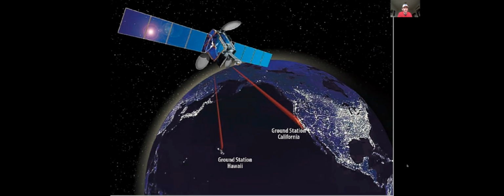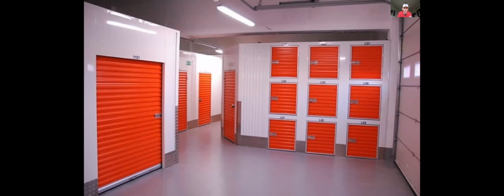So then one more big thing that's pretty important is having some sort of storage mechanism for storing data on your satellite, because oftentimes data collection and data downlink are separate on a temporal scale. So you need to make sure that the data you've generated is stored safely so that you can downlink it when you're in range of your ground station. You can also keep logs of the operational status of your different subsystems so that when you want to downlink them, I see somebody put something in the chat.